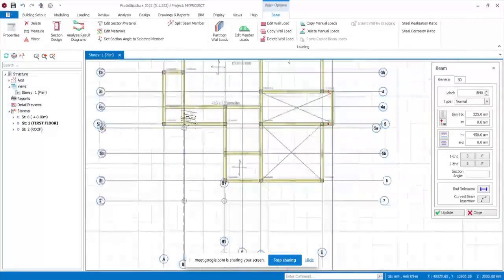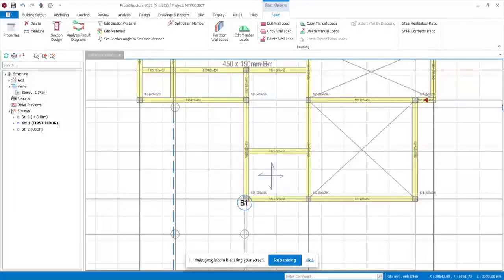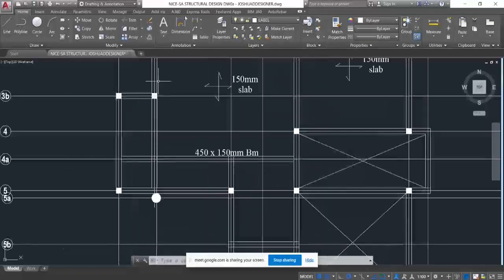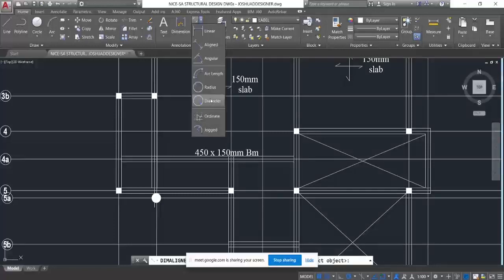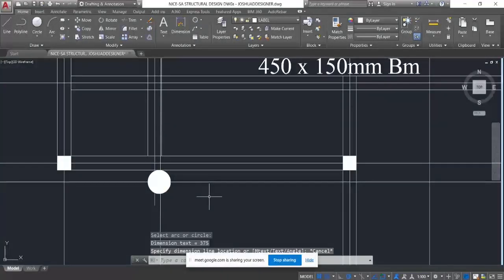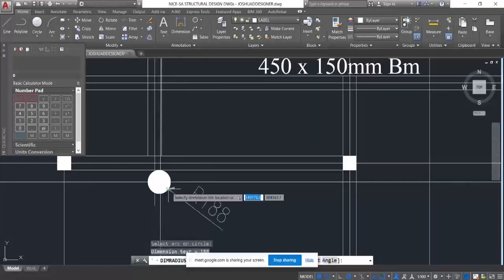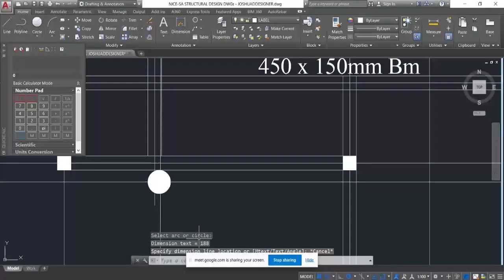Alright. We have some circular columns here. Let's fix them. Let's see what diameter they represent so that we can fix them accordingly. So 375. So that will be 187.5 in radius, if I'm correct. 187.5, yes.